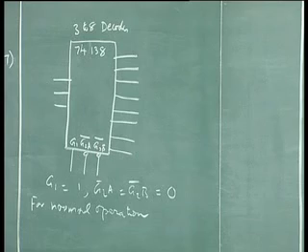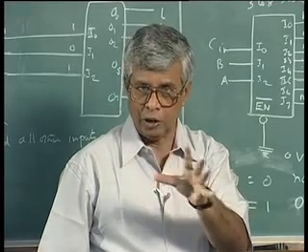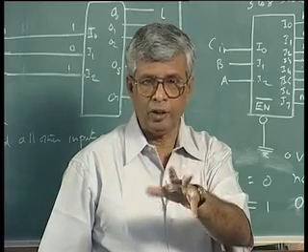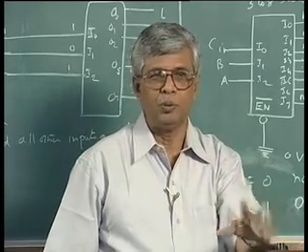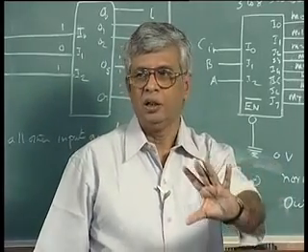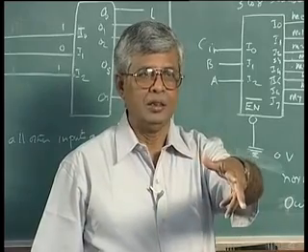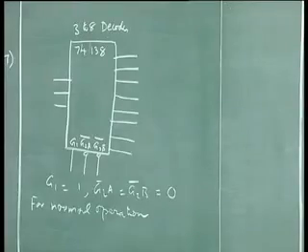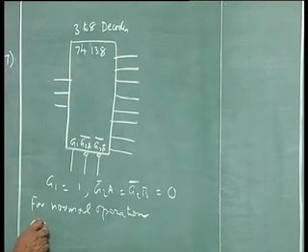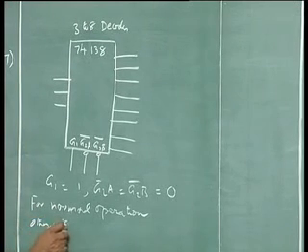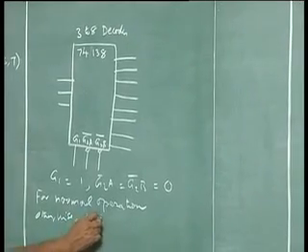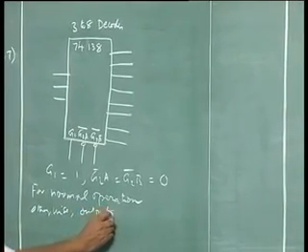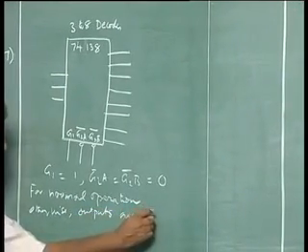Why do you need 3? As I said, sometimes the control signals, I may have to control it from different points of view, from different ways. So I can use these 3 combinations. Only when all the 3 occur as required, only then the normal operation. Rest of the time, otherwise, outputs are tri-stated. Otherwise, outputs are high impedance state. Outputs are in Z state.